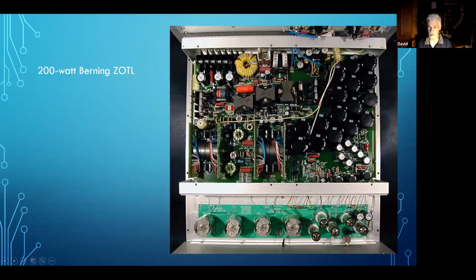Power supplies, I use parallel resonance, not pulse width modulated, but it also does incorporate power factor correction, which is a pulse modulated circuit that's up here. So it's a universal line voltage amplifier that draws its power in sinusoidal waveform instead of high current spikes.